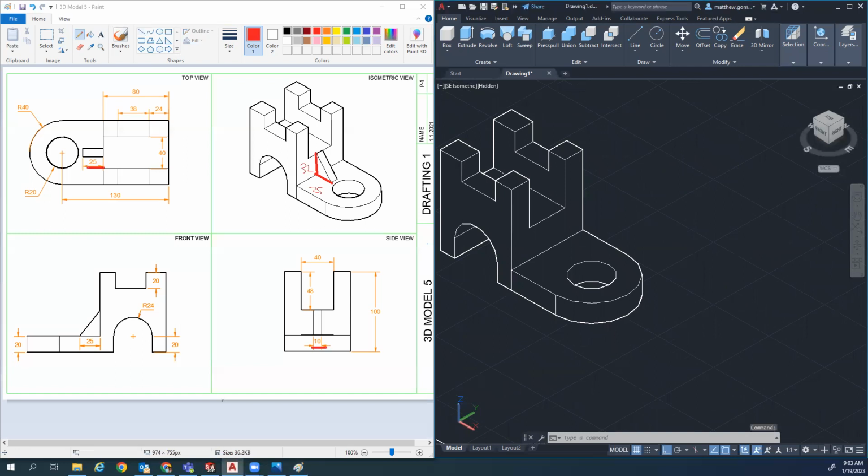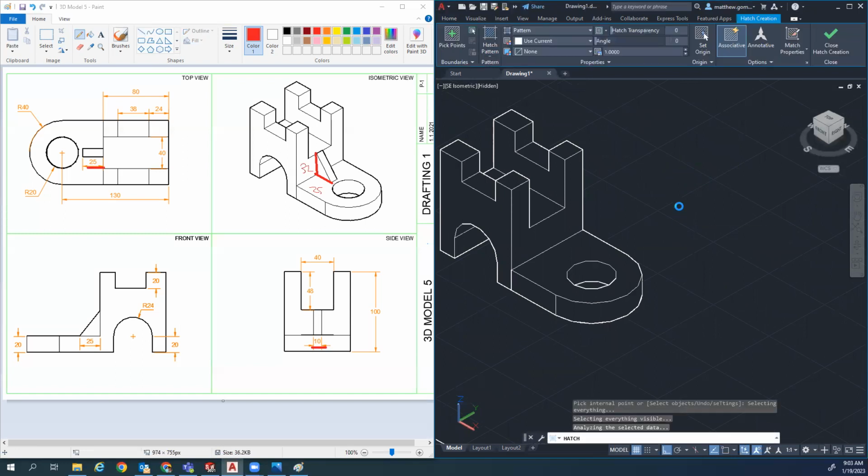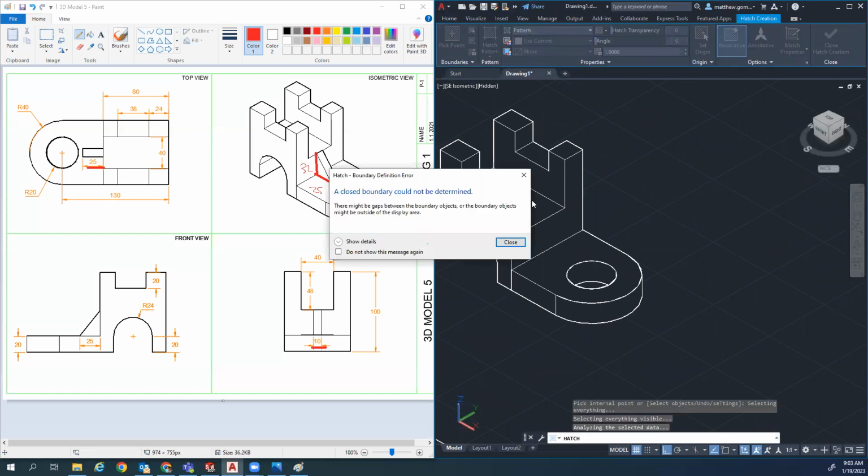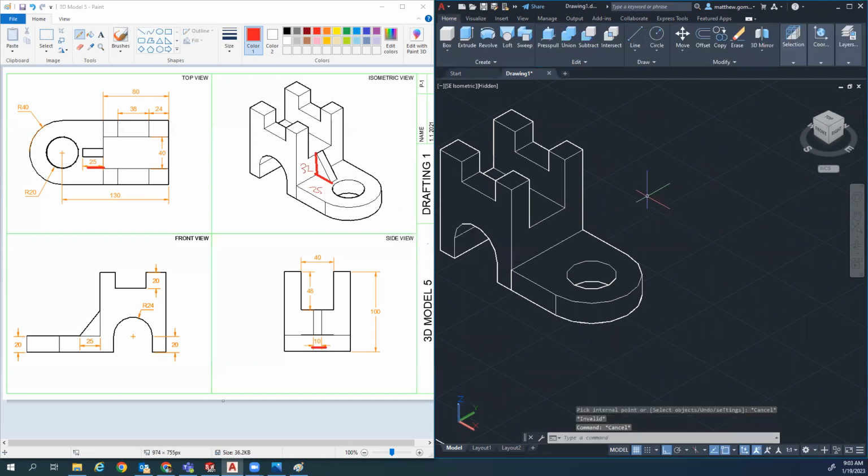So this one I like to just draw out here. Oh no, I think I just froze my computer. Never mind, I hit hatch. All right. Line going down 32, going this way 25, connect the triangle, join it, press pull it back, a value of 10, and then move it into the location where it goes.